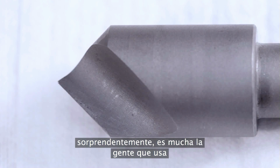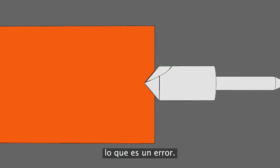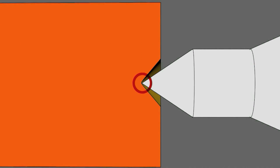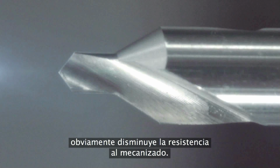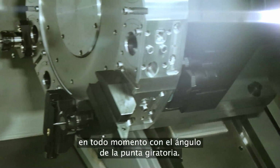And though it may seem like an obvious point, it's worth noting that a surprising number of people will mistakenly use a 90-degree chamfering drill to make their center holes. This is what the contact looks like when a 90-degree chamfering drill is used. With only the bottom edge of the hole touching the center's tip, resistance to cutting loads will obviously be reduced.